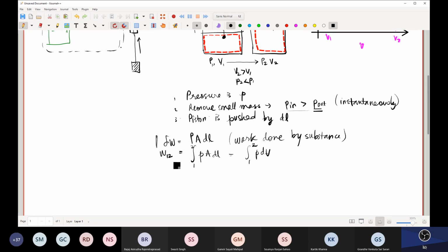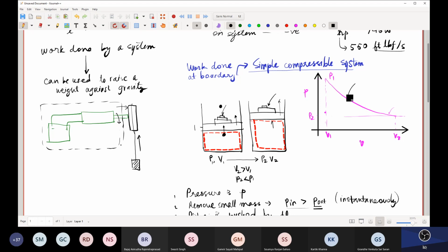Okay, so this is quite simple, and you must now know how pressure changes with volume. You must know this information in order to perform this integration. Now, like I said, this could be obtained experimentally, or you can approximate this to be a certain process. So this curve can be known experimentally, like they used to do for calibrating the automobile engine pressure versus displacement curves, or you can assume a certain model.